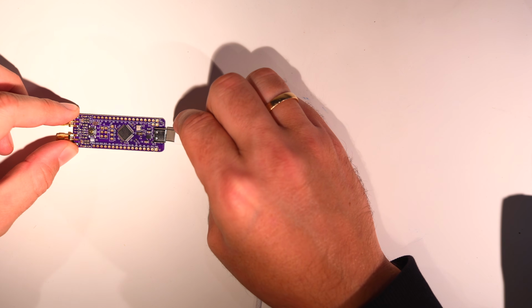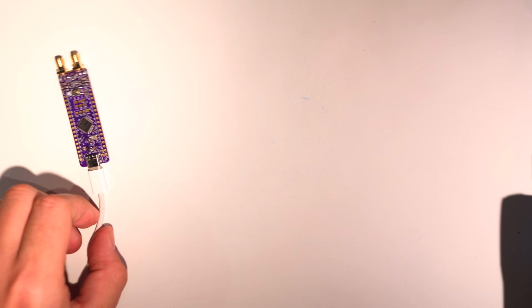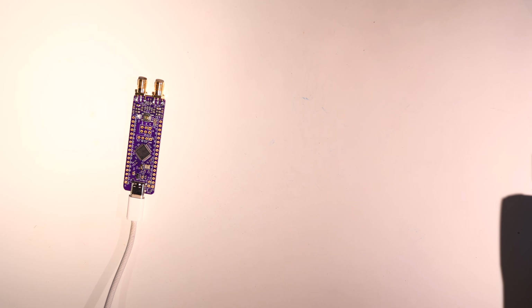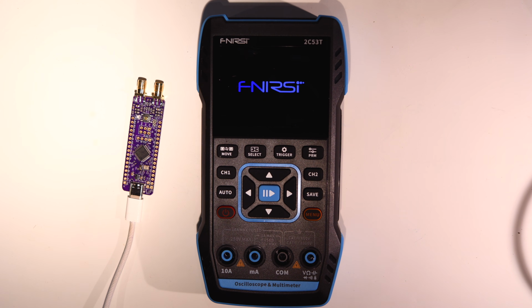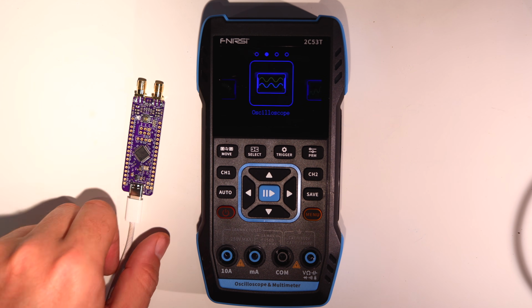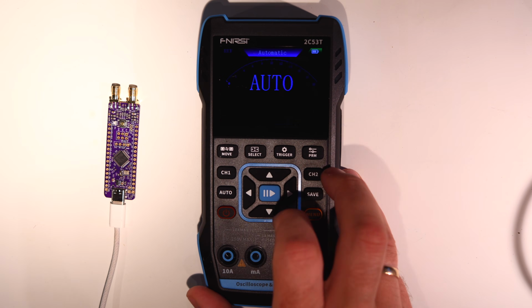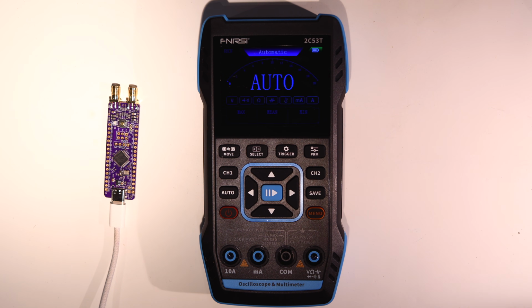I suspect the blue pill boards are usually just double-layer boards without a dedicated ground plane. But with the main feature of this board being the two ADC channels, I decided it was worth increasing the cost a bit to get good separation between the incoming signal and the noisy USB lines going out the other end. The main idea with this board is just to capture the I and Q channels through a passive LC low-pass filter for anti-aliasing. That is, limit the frequencies to what the analog to digital converters can handle, like we went over in the first video.